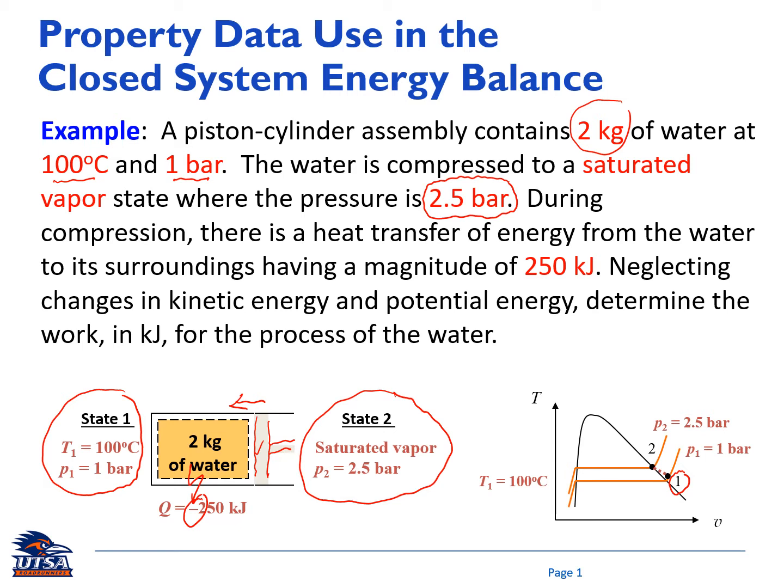You can do the same thing using table A3. Look at table A3, pressure equal to 1 bar, and see the saturated temperature at 1 bar.